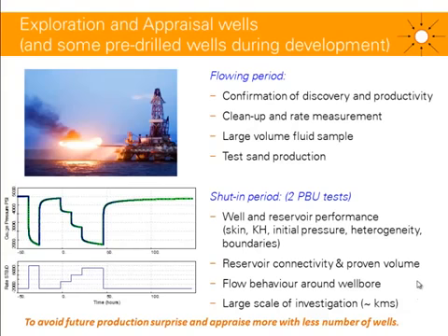What we need to know is that there is no alternative method to calculate the skin, permeability, other reservoir parameters over a large scale of investigation. There is no alternative to get large volume fluid samples and to get information on connectivity over large volumes. So why do we test wells in exploration and appraisal? Well, to avoid future production surprises and to appraise more with fewer wells. So instead of drilling a well a kilometer away, you can just test it and you will have a large scale of investigation.